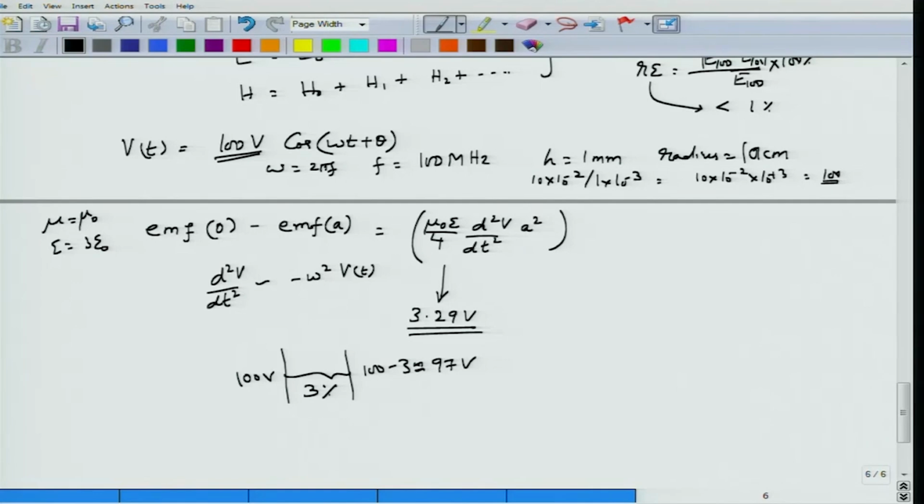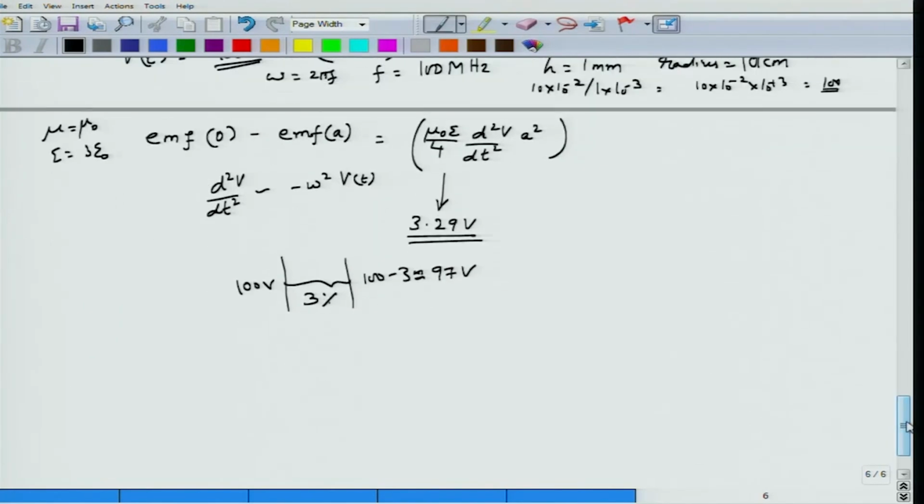You had a capacitor, and you can show that the capacitor actually also includes an inductor in its equivalent circuit because of this non-uniform effect, but that is something that we will leave for an exercise. The point here was that you can construct the solutions of E or H using quasi static up to the desired order, up to desired accuracy, that would be a better word to say. Thank you.